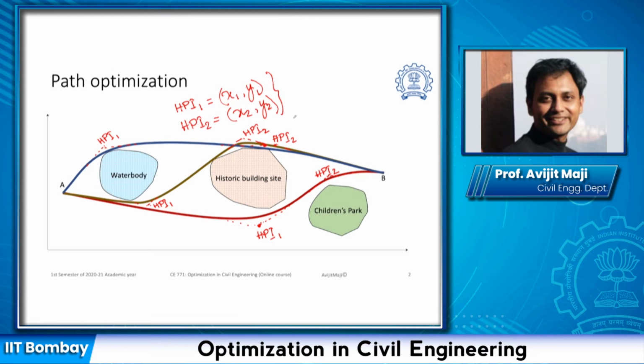So the alignment cost, which possibly includes the length dependent cost and the land acquisition cost, we can easily consider the length dependent cost. If we know the coordinates of this location or any of the locations, we can easily find the length of the alignment by knowing the radius of the curve fitted at each location, then understanding the length of the tangent portion of the curve, and then calculating the total length. So it was easy to represent if I know my x and y coordinates.